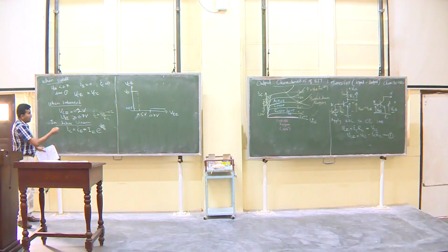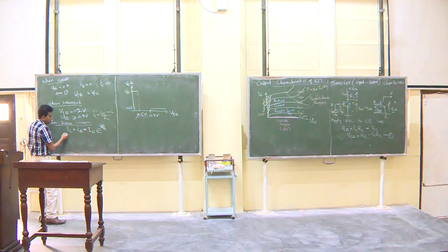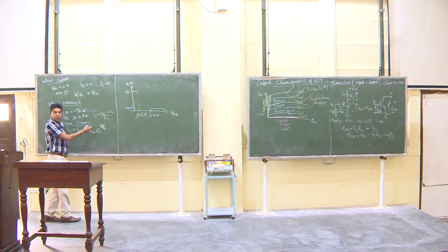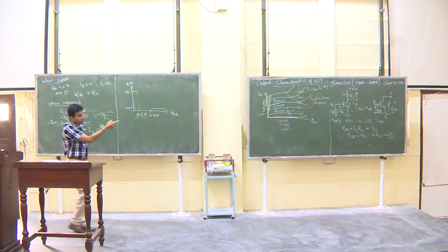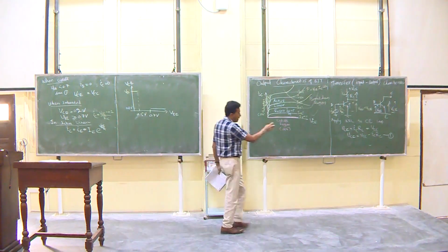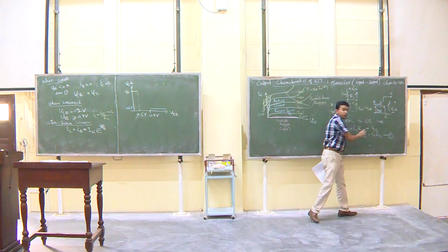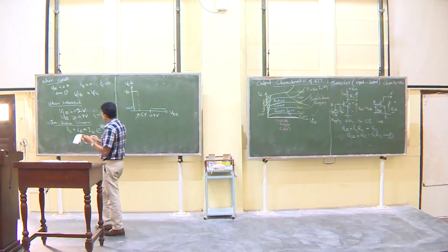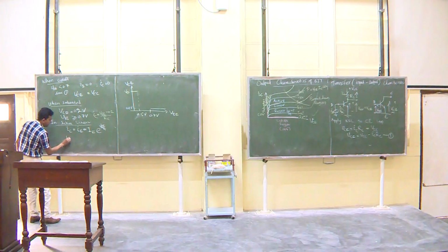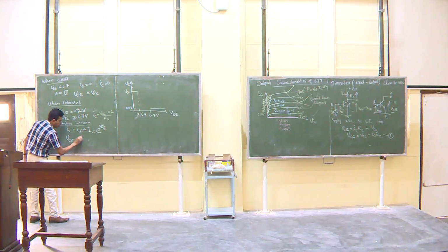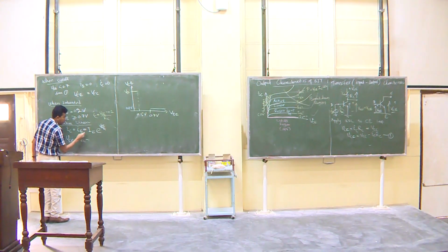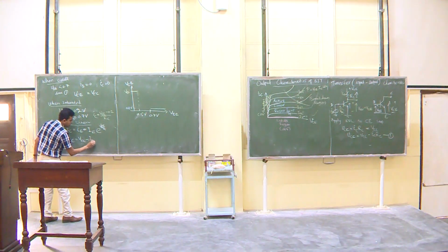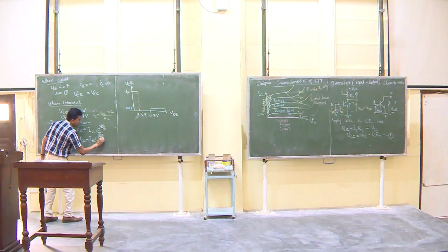Now, in place of IC I have this, so in that equation number 1, I can replace IC with this nonlinear component. Up to this everything was linear, nice. But now, when I replace this, VCE is equal to VCC minus IC, which is basically IS, picoamperes, some small value, e to the VBE divided by VT.